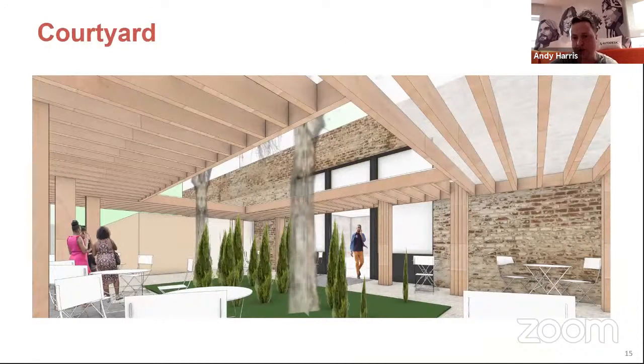So this is an image just showing what that area could look like. We wouldn't put seating in the middle there because we know it's an inlet, and we don't want air coming across tables from the inlet and then going across other tables to an outlet. So we looked at that as a courtyard in the middle where nobody would sit, but they would sit around the outside where the inlets are. Go to the next slide.